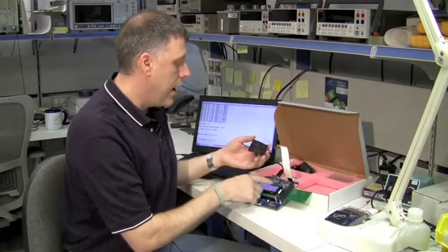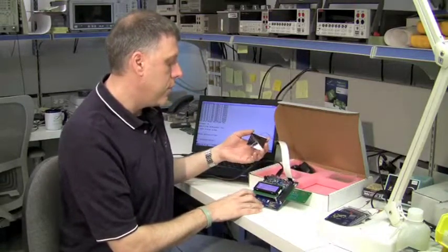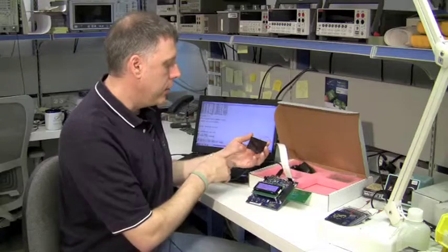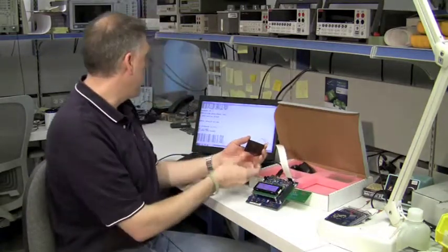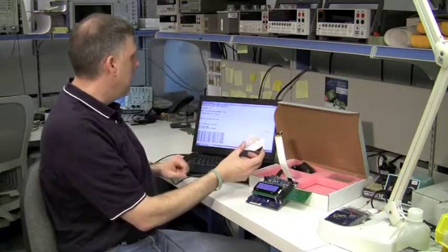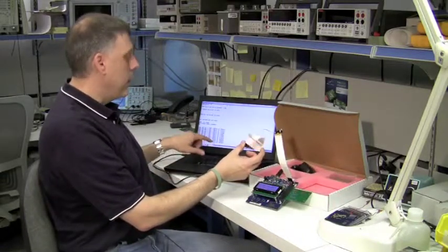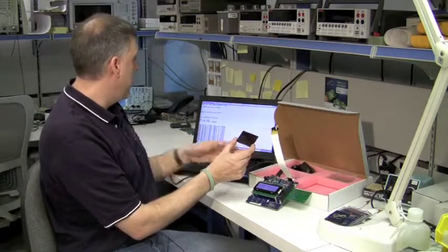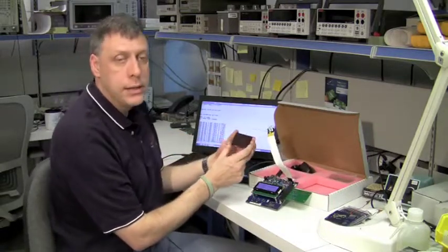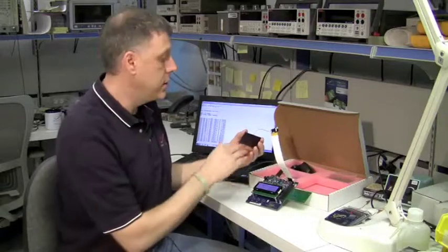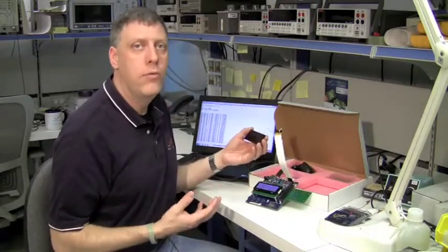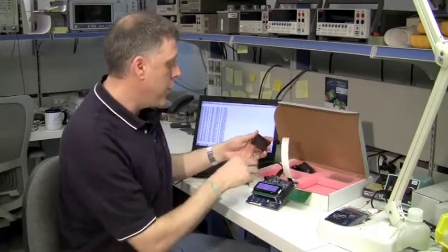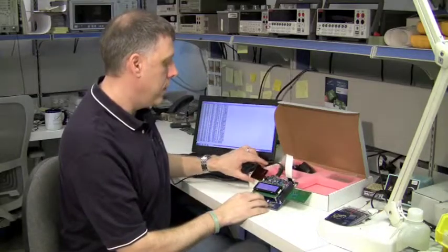So in this case, I have the pass-through mode set, so I'll start my recharge. And right here what I'm seeing is that I'm getting 4.06 volts on the MEC, and I'm getting 190 microamps, and I'm logging it over here on my laptop as well. So this solar panel is actually doing pretty well right here. It's producing almost a milliwatt in this indoor lighting, which is pretty good. This is a solar panel that is tuned towards indoor lighting, which is fairly common for many of the energy harvesting type applications.